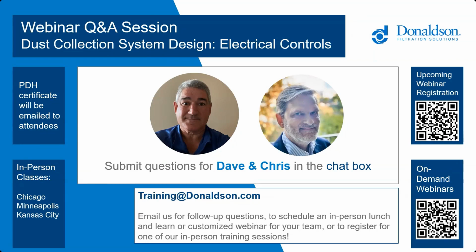We use inlet isolation valves, if that's what they mean, explosion isolation valves. That would be separate. If there's an explosion in the dust collector, it allows it to vent through either flameless venting or through the explosion vent externally from the building. That would be an explosion isolation valve. We use them quite regularly.